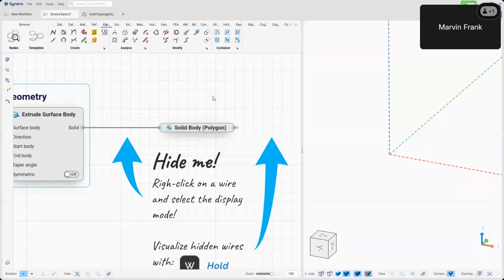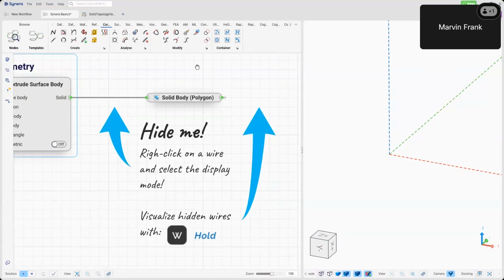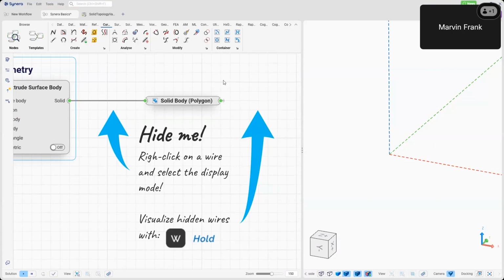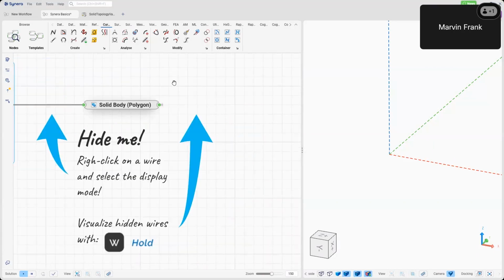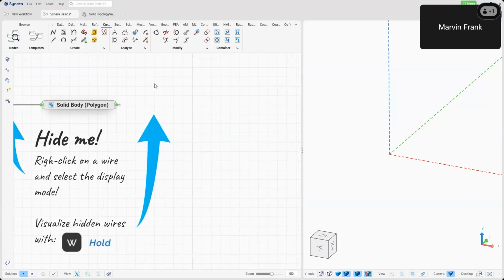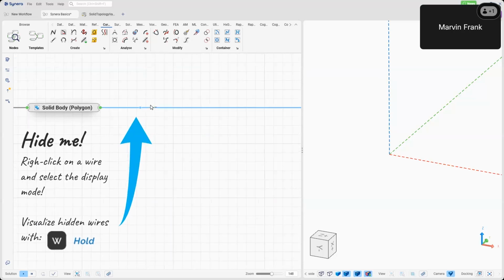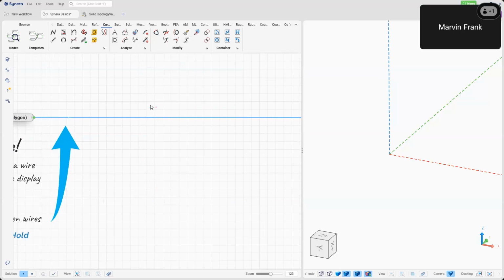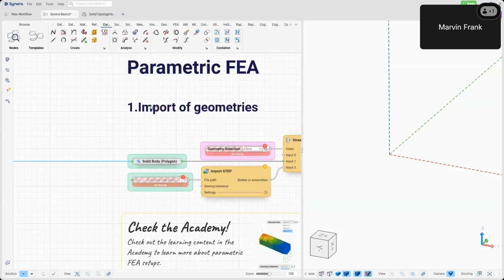That's another very, very important key command here. Okay, here we see that this wire leads somewhere. So let's go and check it out. What's on the other side? I will press W, check the wire, and then with Control and the arrow buttons on the keyboard, I can jump to the start or to the end of that wire.